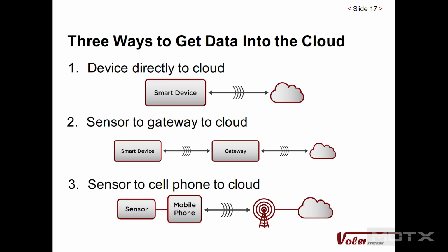What is typically done is you have a sensor like Bluetooth or Bluetooth low energy that connects to the cell phone that you're wearing. It only has to transmit a few feet. And that goes directly to the internet. And that's pretty much the standard today. In the future, we're going to see technologies, they exist, but they're not widely spread, which can send low power and low speed transmissions directly to the internet over several kilometers.